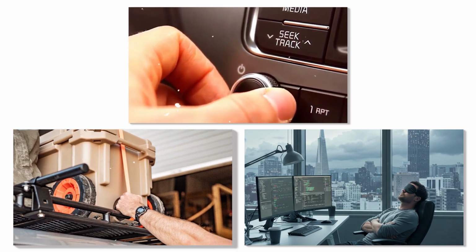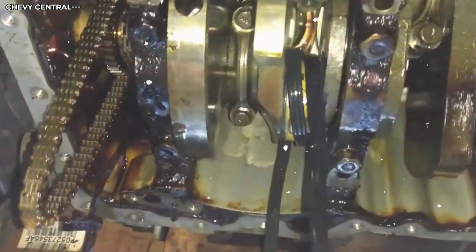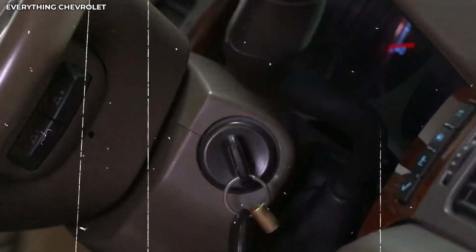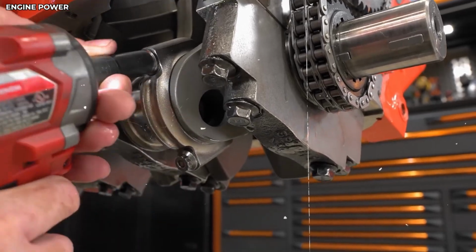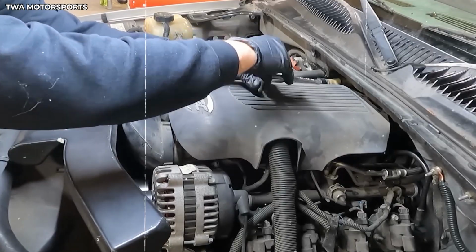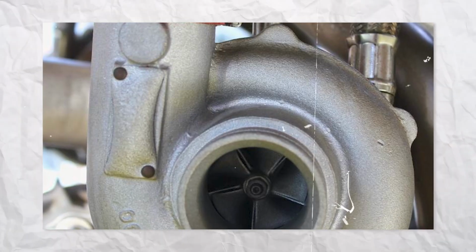The tow haul mode trick works similarly. Tow haul mode on F-150s and Super Duties delivers the most aggressive throttle response and transmission behavior because the computer assumes you're hauling heavy loads. If you reset adaptive learning and then drive in tow haul mode for a week without actually towing anything, the computer learns extremely aggressive characteristics. Switch back to normal mode afterward and you'll have incredibly responsive throttle and transmission behavior.